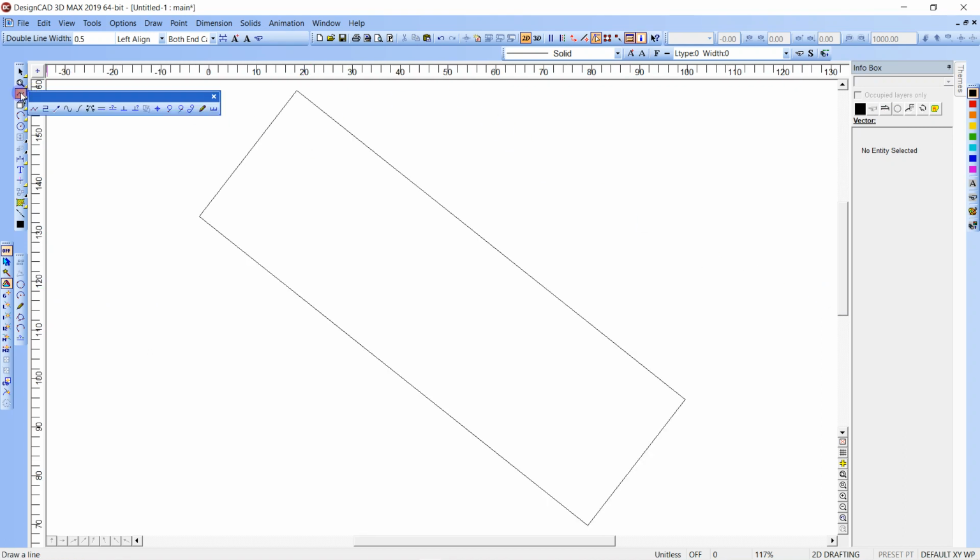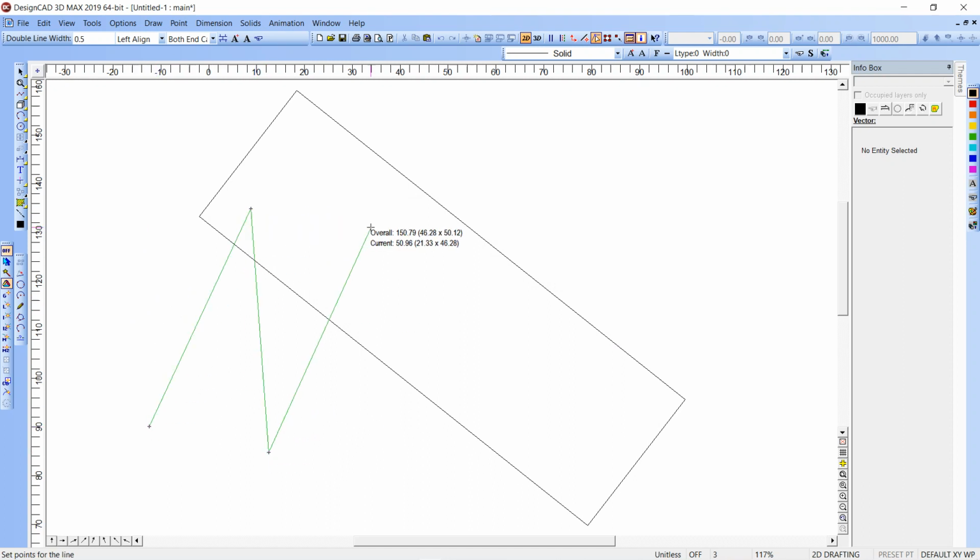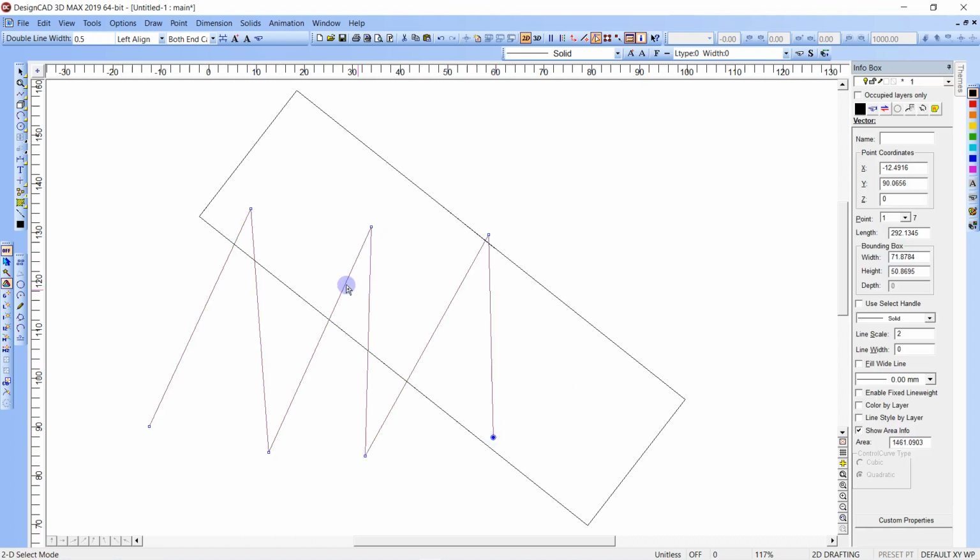How about let's go into this one. This is the main tool. This is one they use probably more than anything. So there's the line, and the shortcut key for that is L. No, sorry, that's AutoCAD. B, and it'll give you an option to draw polyline, enter. So this is automatically a polyline.